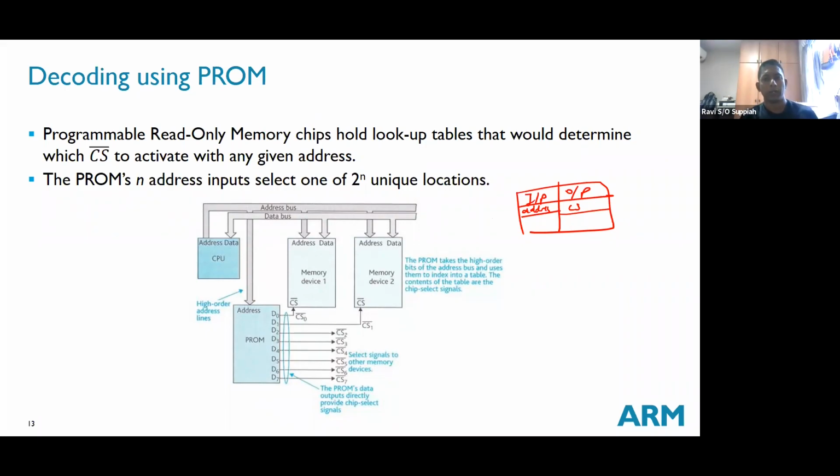For more complex devices like microcontrollers with a lot of subsystems and peripherals, this is probably the approach to take, because you have a lot of subsystems and a lot of registers. To design the circuitry from the ground up is going to take a lot of effort, whereas if you put everything in a lookup table in software, it's a lot easier. Let the FPGA handle all this translation of address to the chip select or register access pins.